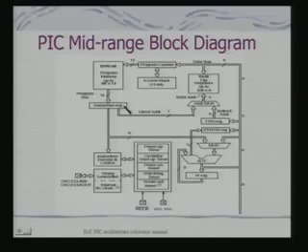But typically in 8086 or such processors, stack is part of your main memory itself. This is your instruction register. Now this instruction register's basic job is to take the instruction. The instruction would correspond to what? The instruction whose address is provided by the program counter. This instruction is decoded by this block to generate what is called the control and the timing signals for the internal block of the PIC processor.